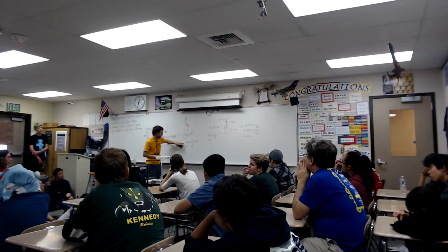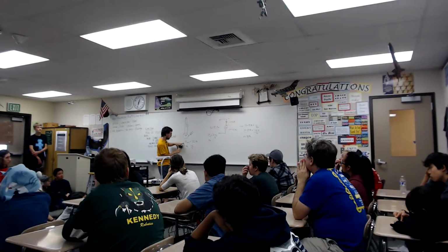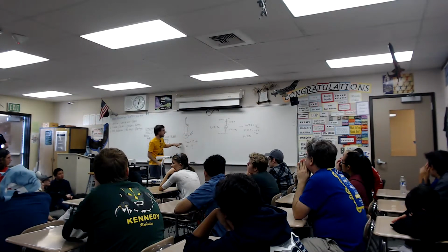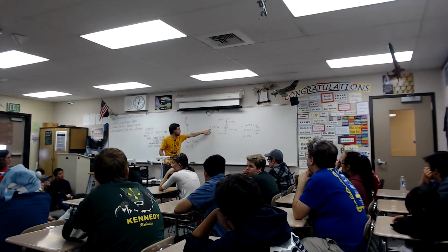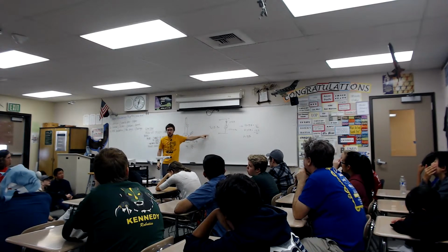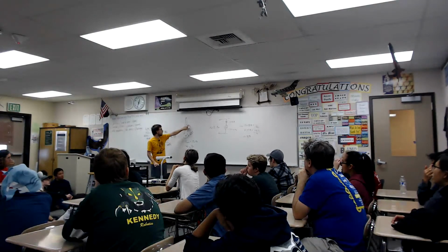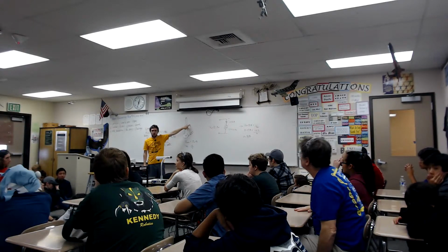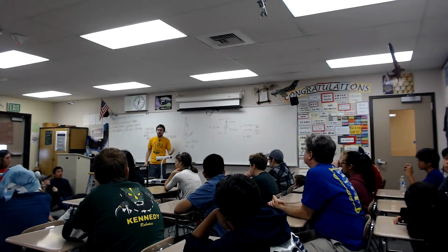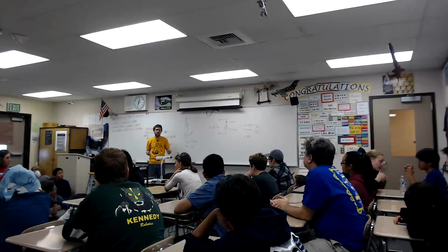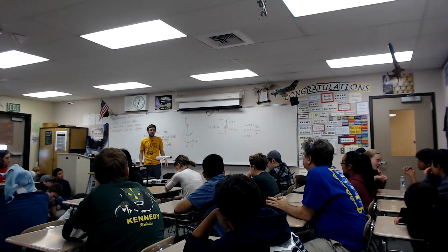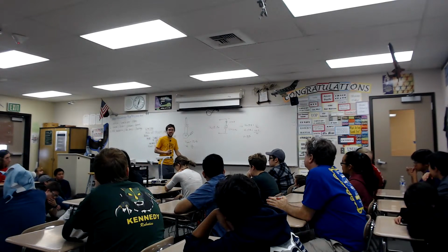Okay, let's back through it. Let's try that again. I'm trying to get rid of motor torques and get us all into shaft torques so that we can then convert that eventually to, we just want to have our equation in the output terms, because we care about where the output is, right? Our elevator is at position 1 meter in the air, accelerating at this rate. We don't really care about what our motor's doing. So that's our end goal.